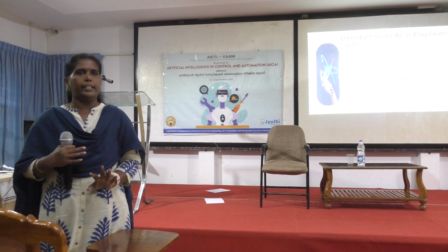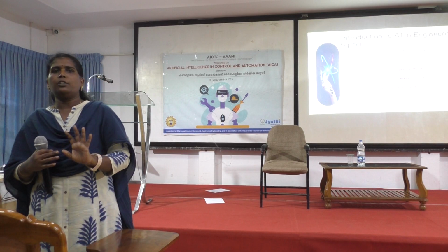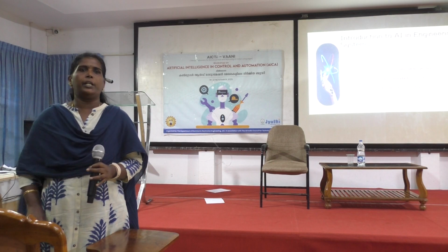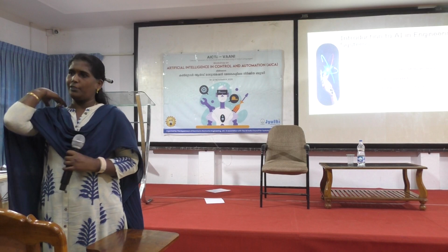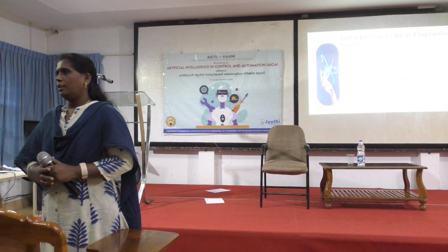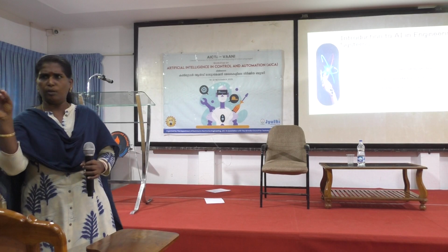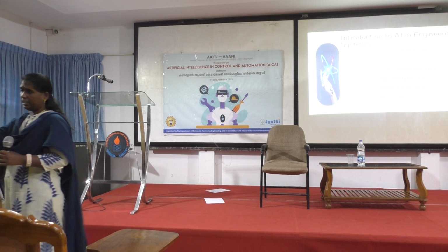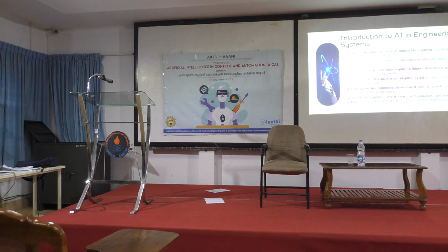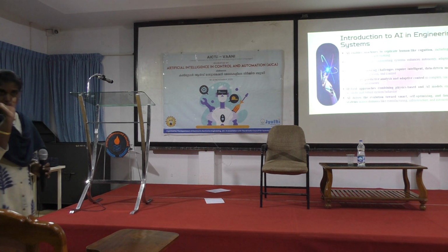If you are using PID control, okay, what is the formula for PID control? The mathematical equation of PID control is Kp times e plus Ki times the integral of e, plus Kd times de/dt. So this is the mathematical equation.